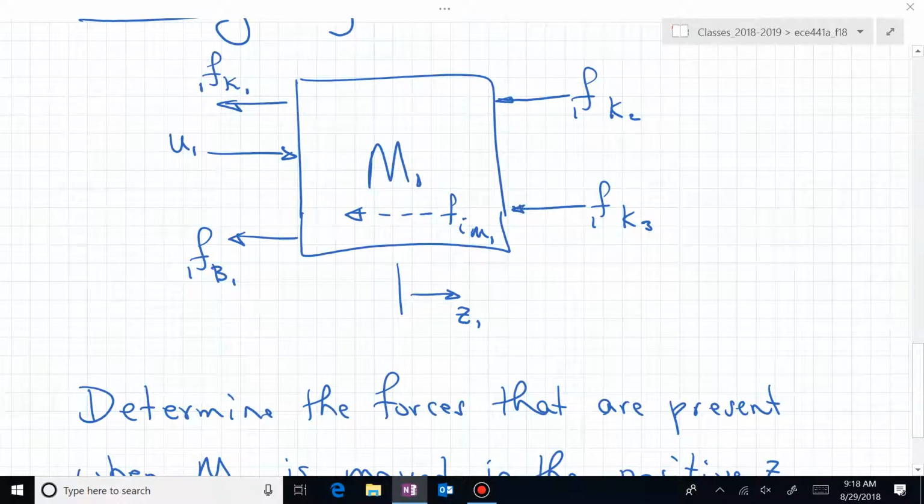Here we have forces to the right equal forces to the left, is another way of saying that. And then we could say, okay, what are those forces? Let me just start writing the force expressions, and then we'll write the equilibrium equation, and then we'll plug in the force expressions to that. That's the order that I'm going to do it.